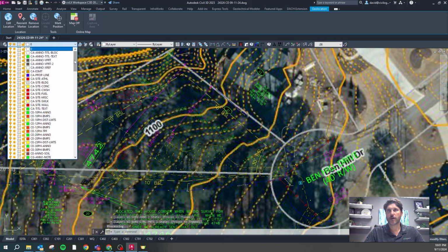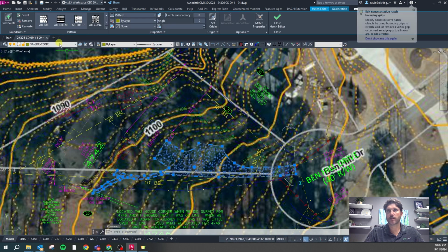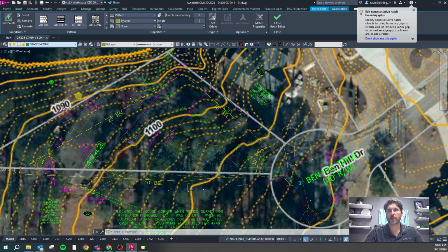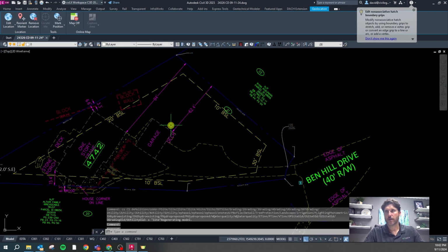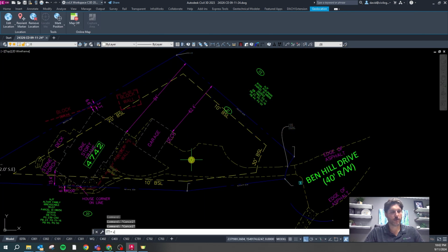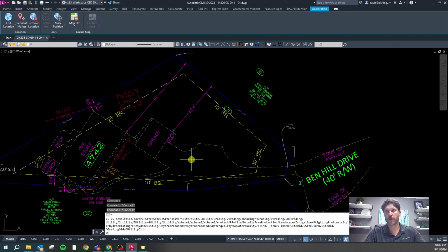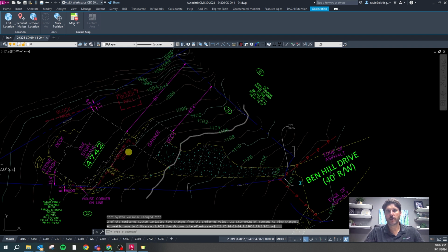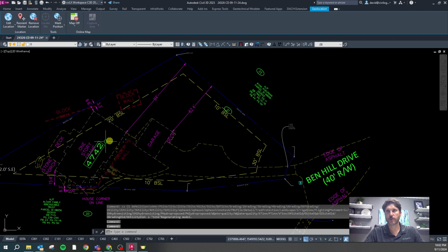And now if I go in here, all these layers are back, and there's a bunch of VD demo ones, and there's VD site concrete and building. So if I take this site concrete and I put that on the demo layer, now it's gone on the site plan. I go back to the M for demo or existing conditions, and it's there. Note that I haven't put these things on a demo layer, so when I go to the site plan, they're still there.